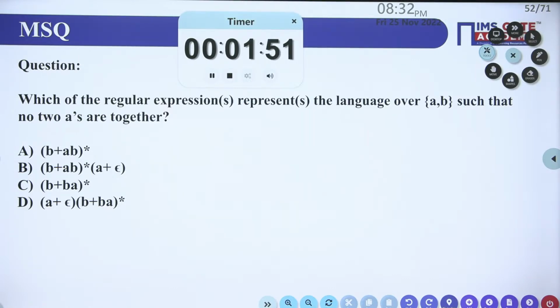Are you getting me? There will be a vertical force due to this, P sine theta, and due to this also there will be P sine theta. So you can clearly say that 2P sine theta is equal to 12 kilonewton, because of balancing. Now, tan theta is equal to e over L. Now, what is e?